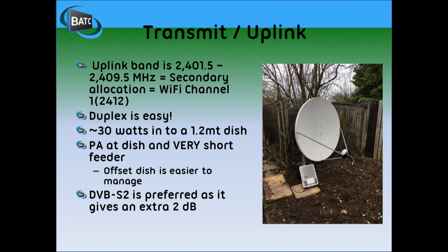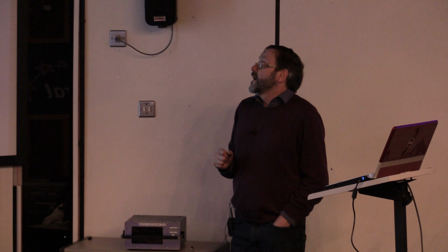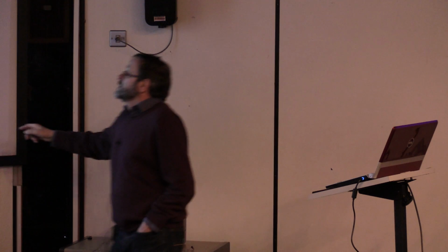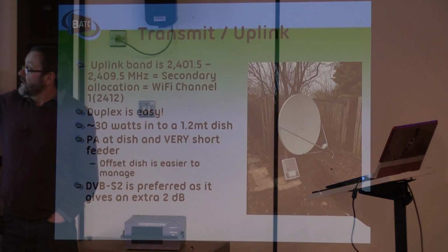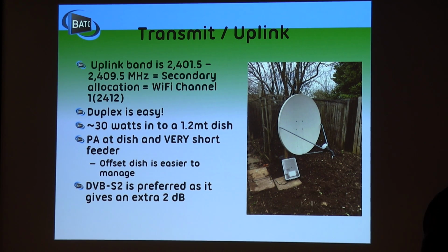The great thing is duplex is easy because you're on different frequencies, so duplex is great. I've got some numbers in a minute, but you're talking about 30 watts into a 1.2 meter dish. That's my particular setup. But you'll notice one thing, the thing that us microwavers know: the piece of wire between the antenna and the PA has got to be kept really short.